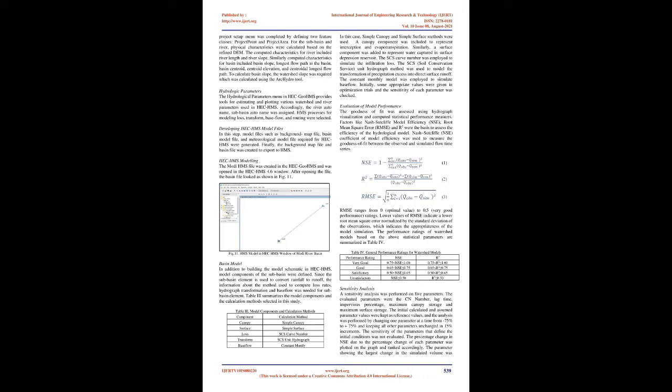Evapotranspiration. Evapotranspiration is responsible for returning approximately 50 to 60% of precipitation to the atmosphere. For this study, the monthly average evapotranspiration was obtained using Thornthwaite, 1948, equation at the subbasin level and calculated accordingly. Fig 7 shows the line chart of average potential evapotranspiration, PET, of the Modi River Basin based on the temperature by using Thornthwaite method.